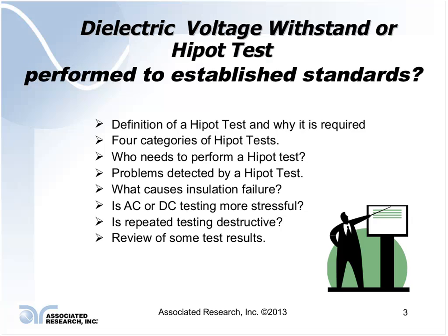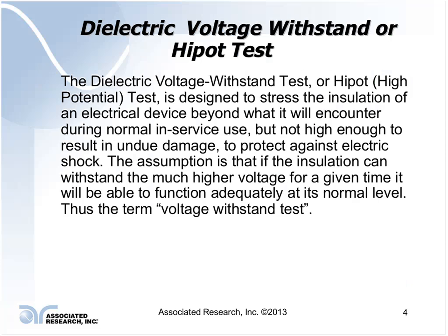So, with that being said, what is a Hipot test? Hipot is essentially an acronym for dielectric voltage withstand test, a high potential test. This test is designed to stress the insulation of an electrical device beyond what it will normally encounter during in-service use.